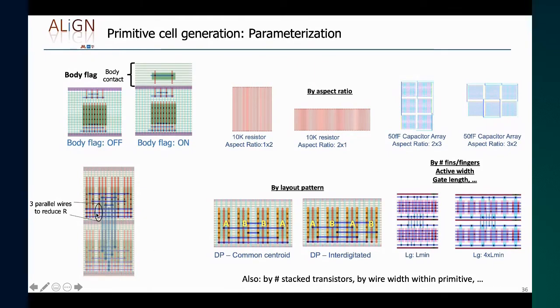We can use multiple parallel wires. This turns out to be really important in FinFET technologies because wires are very resistive. So if we use multiple parallel wires, we effectively reduce the resistance of the array structure.